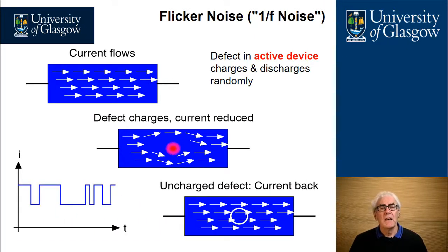The effect of this is we get sharp increases and decreases in current. So here we've got the current flowing through the junction, and we've got high current. We have a noise trap at this point here. It is then released back into the current flow. The current increases again, then some more traps happen, and we land up with discrete changes in the noise due to this concept called flicker noise. And it's really all fundamentally down to the quality of processing, how you actually manufacture your transistors.